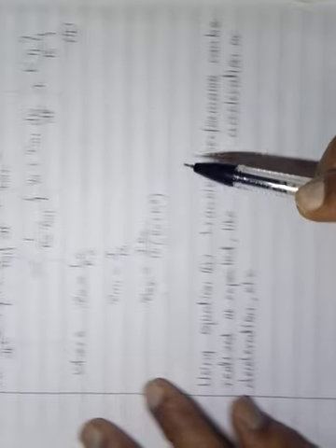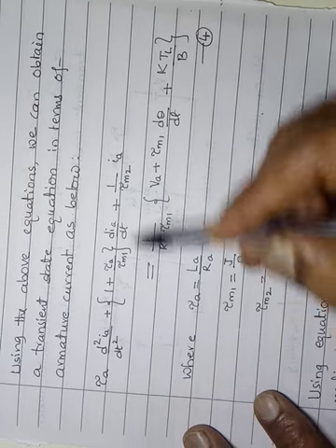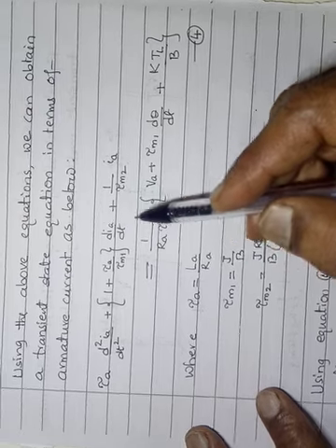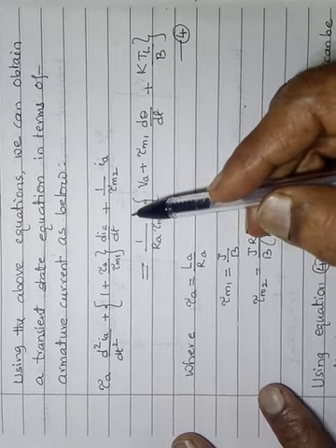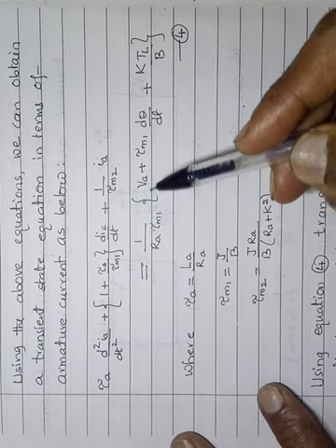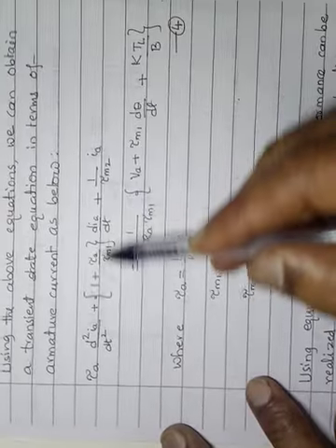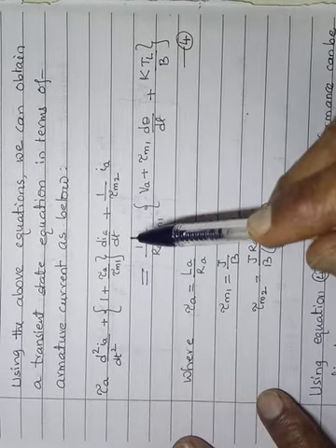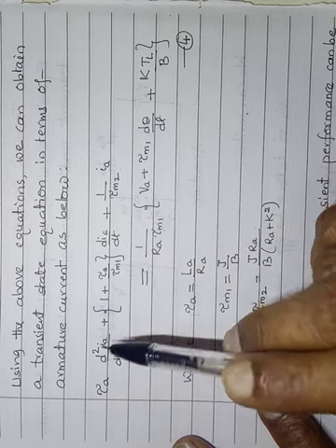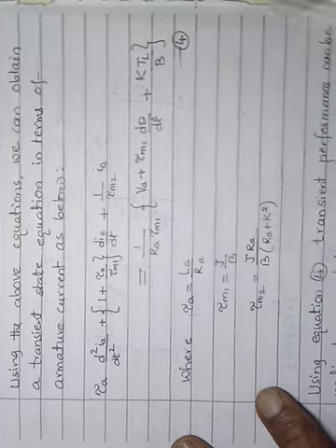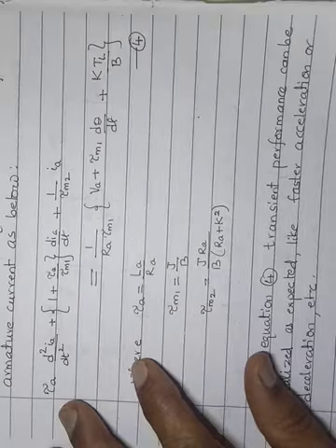We can realize a particular d theta by dt. How much di by dt do I have to have? To have that much di by dt, how much voltage should I apply, and over how much time, how should I increase that? That way I can link it with the control. So this is the transient equation representing the separately excited DC motor, wherein we have both electrical and mechanical parameters. So that's regarding the transient performance.